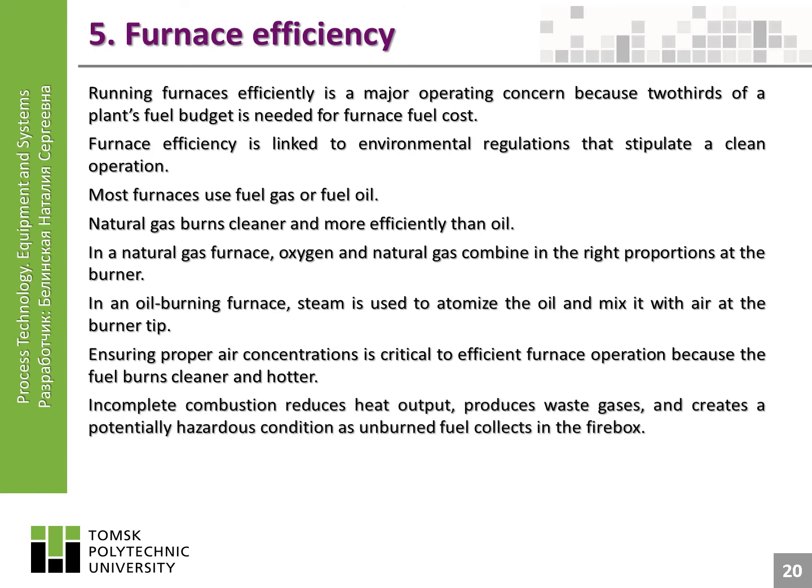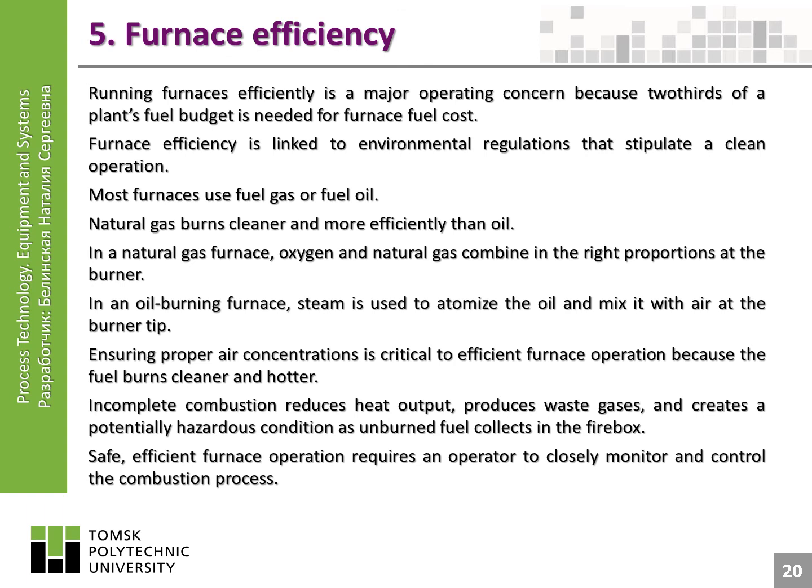Incomplete combustion reduces heat output, produces waste gases, and creates a potentially hazardous condition as unburned fuel collects in the firebox. Safe, efficient furnace operation requires an operator to closely monitor and control the combustion process.